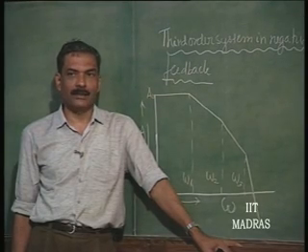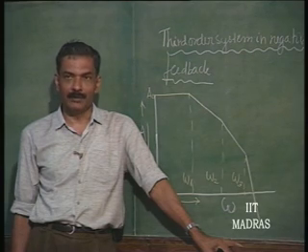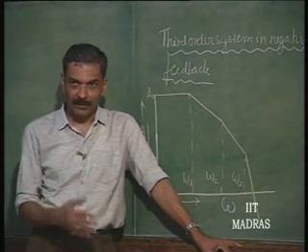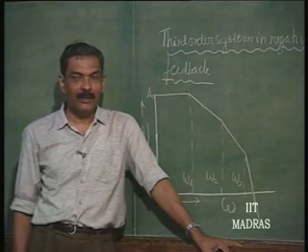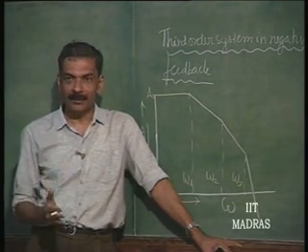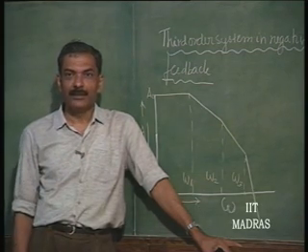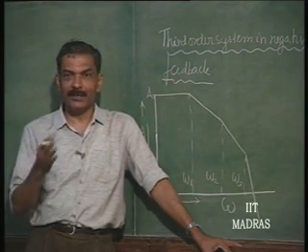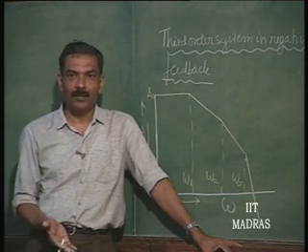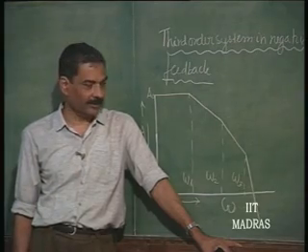So, now let us consider the third order system put in negative feedback. We have so far considered first order and second order. What happened in the first order was the bandwidth improved in such a manner that gain into bandwidth was a constant. What happened in the second order system was that the poles, which were originally lying on the negative real axis, got shifted to complex conjugate pairs, and they could come very close to the imaginary axis.